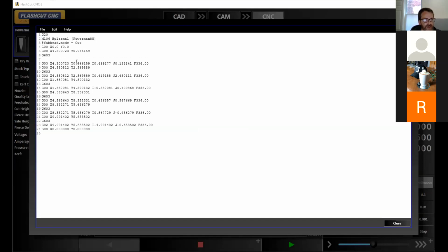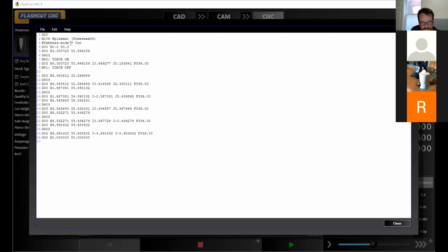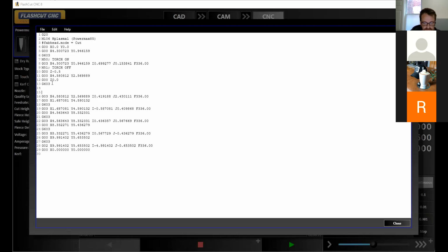Okay, we have after our G603, we got M50 torch on. After this line, we have our M51 torch off. Raise our torch. This is our next position. Okay. Let's tell our torch to turn on.